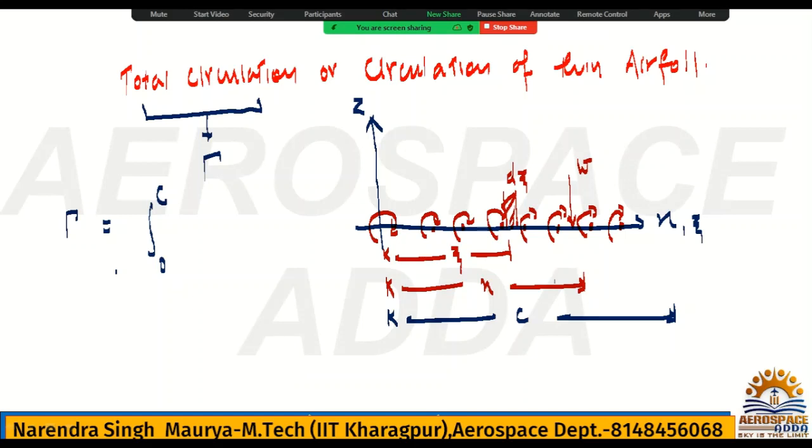and that vortex sheet will be represented by small gamma, along the chord, and this axis is the xi axis. So it is nothing but gamma of xi into d xi, for this segment you are calculating d xi, for this length. So this is nothing but total circulation. Always remember, this is nothing but total circulation.